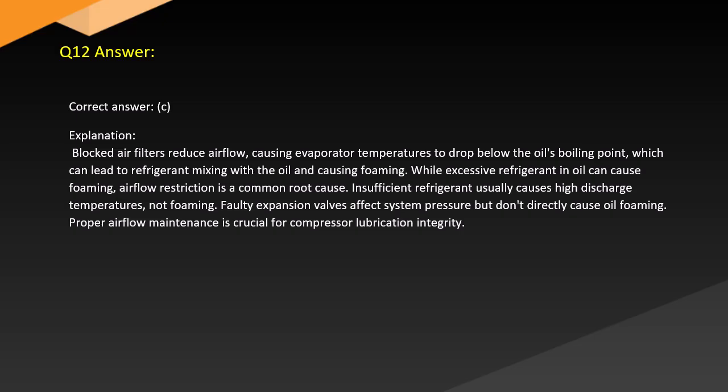Insufficient refrigerant usually causes high discharge temperatures, not foaming. Faulty expansion valves affect system pressure but don't directly cause foaming. Proper airflow maintenance is crucial for compressor lubrication integrity.